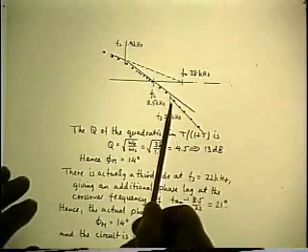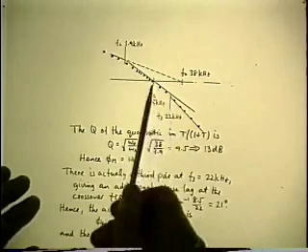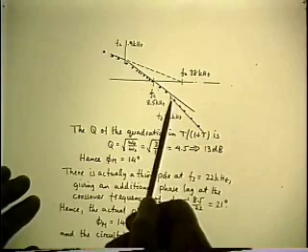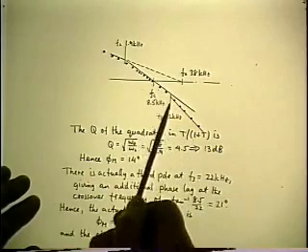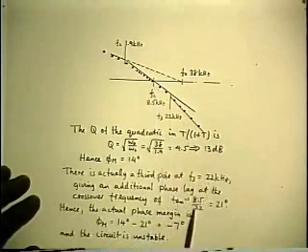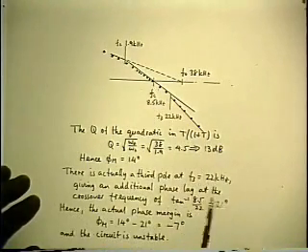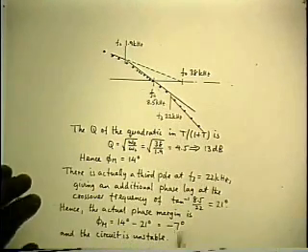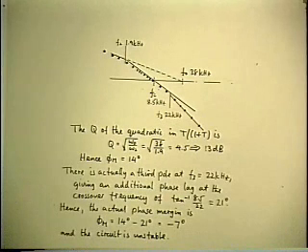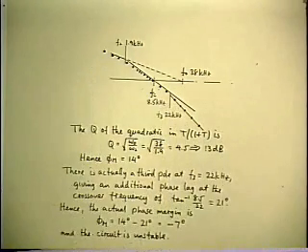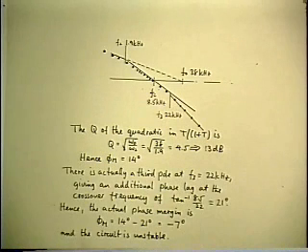Now, does that confirm that it should have been unstable? Yes, it does, because the original phase margin was 14 degrees. But the third pole is going to contribute an additional phase lag at the crossover frequency of arctangent 8.5 divided by 22, which is 21 degrees of phase lag. So the phase margin becomes -7. Therefore, it's unstable. So the benefit we have from all this is that we've identified what the mistake was. Now you have to track that back and see why it happened.